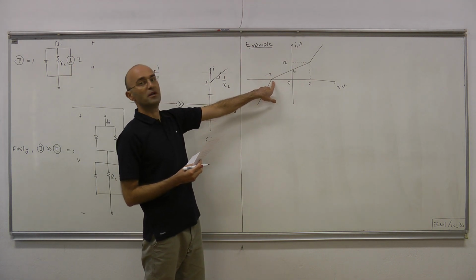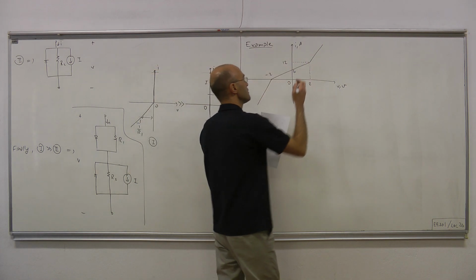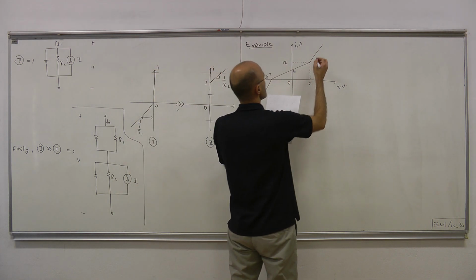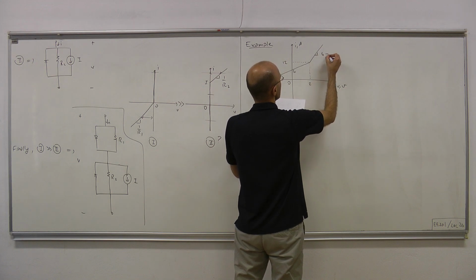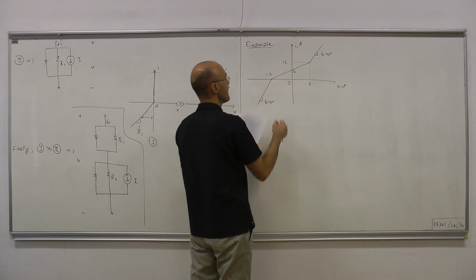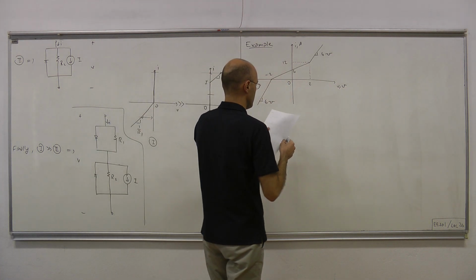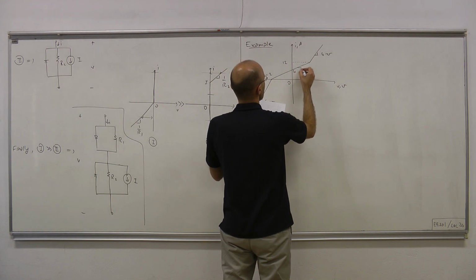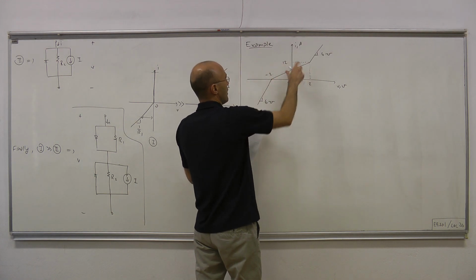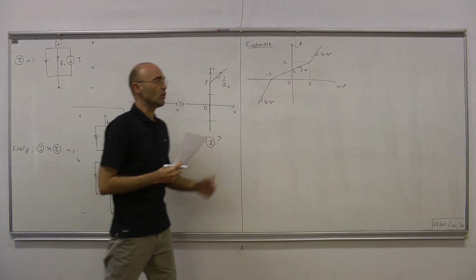Here we have one discontinuity in the slope, and here we have another discontinuity in the slope. The slope here is given to be 6 mhos, and here the same 6 mhos. Okay, and between -2 and 2 volts, the slope is half, that is 12 over 4, we're talking about 3 mhos of slope.